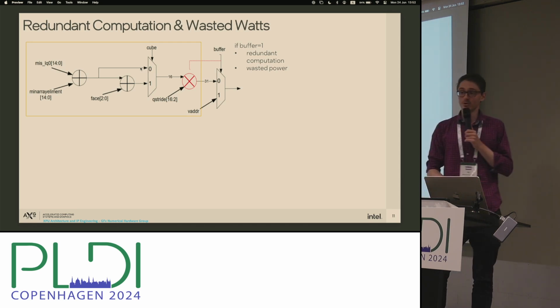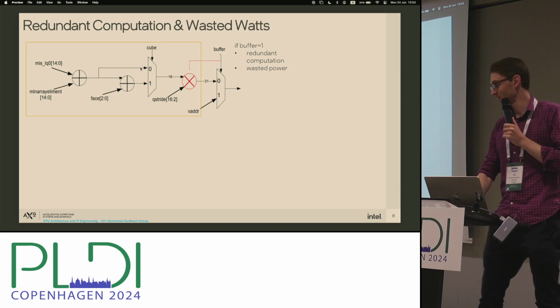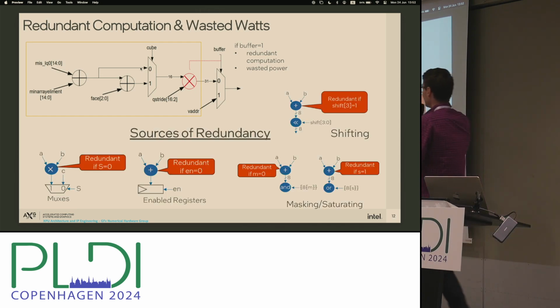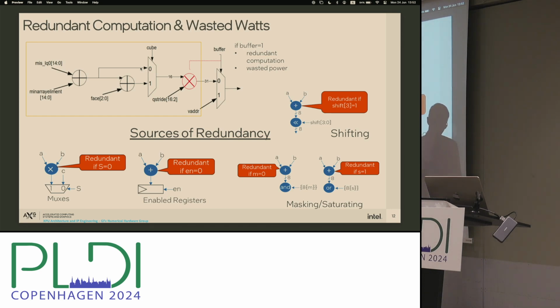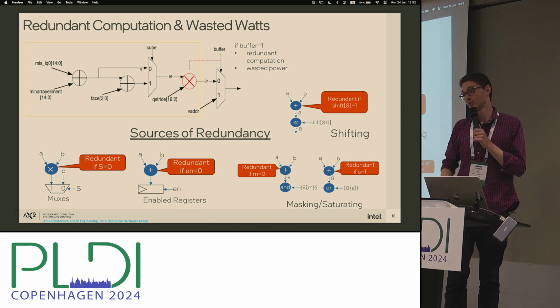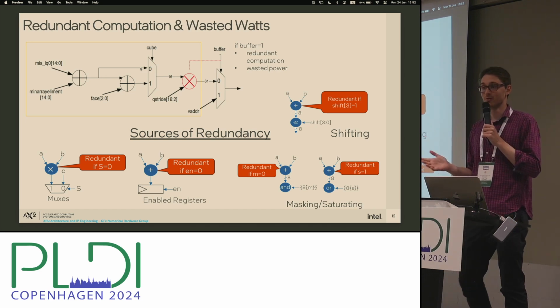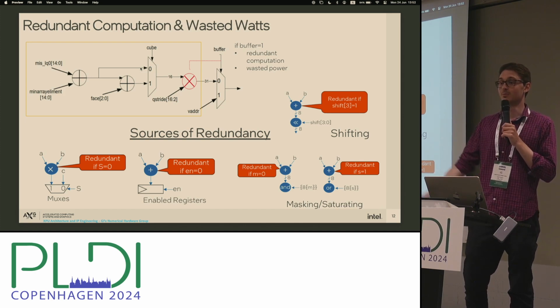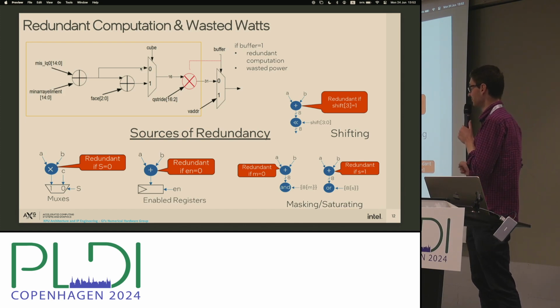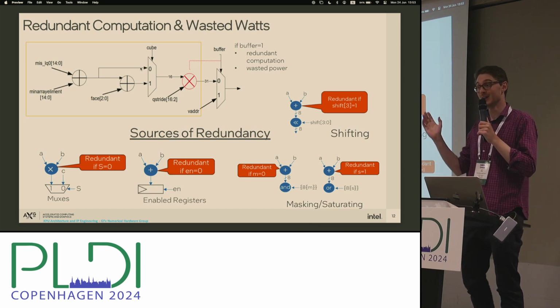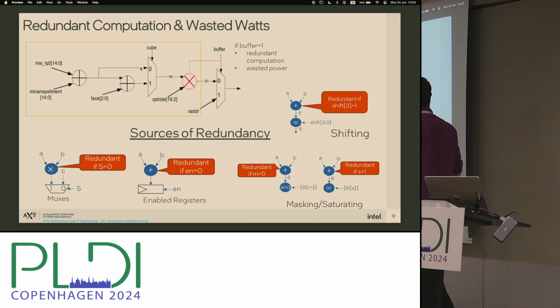So what we traditionally will do in hardware design is insert these data gating operations where we can basically say we're going to zero one of the inputs to the multiplier, and that means most of the gates throughout your multiplier circuit are not actually going to toggle, and so you're not going to consume any power. Woohoo, you've saved a bunch of power. You didn't do a redundant computation. You just produced 0 when you could have produced the actual correct result, but you didn't need it, right? So why would you waste the power?